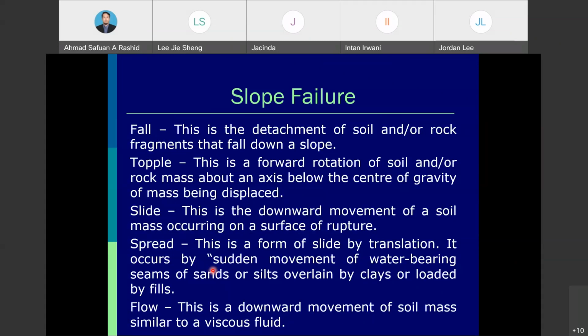Actually, I have been involved in these debris flow problems, whereby the government wants to build what we call a sabo dam. Sabo dam is a term in Japan, while in Hong Kong they normally call it a check dam. It can minimize the effect of this debris flow, because this dam will catch or capture the debris movement before it reaches any residential area down the hill.